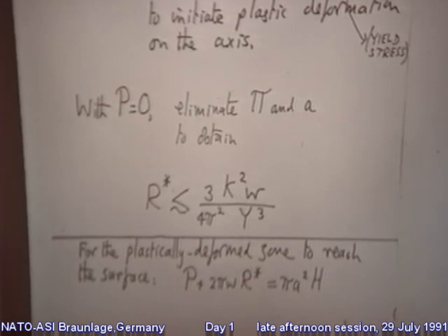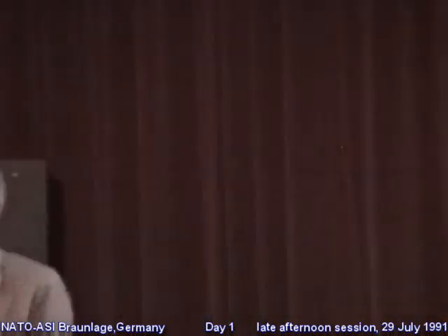And by the way, I'm just talking about the initiation of plastic deformation. I'm not talking about full plasticity. Pi, as we've seen, is proportional to area to the 3 halves. And therefore, if you go to smaller and smaller contact sizes, both the force required and the attraction force get smaller. But the attraction force won't get smaller quite as fast as the force required to initiate plastic deformation. And therefore, provided you go to a smaller contact area, you're bound to have some plastic deformation.